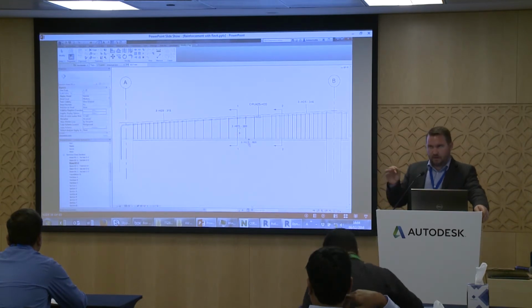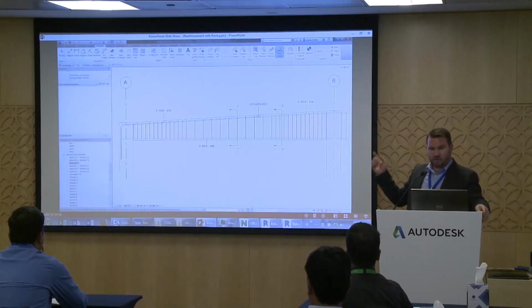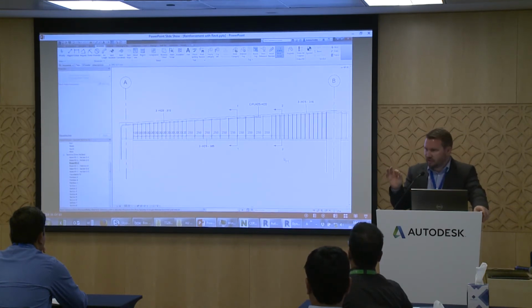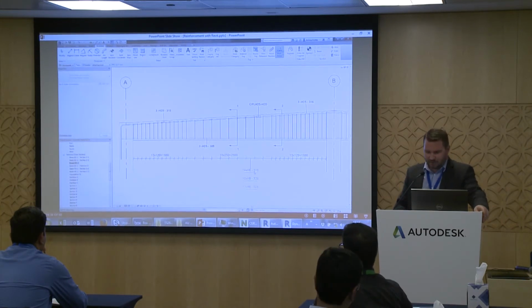So that's why it's important, if you have free rebar at the bottom, to create the free rebar with the option free. If you create 111, when you annotate it will be the same in 2D and 3D, but when you put your tag, it will show 1. Okay. And here after you can put the value and all you need to explain.